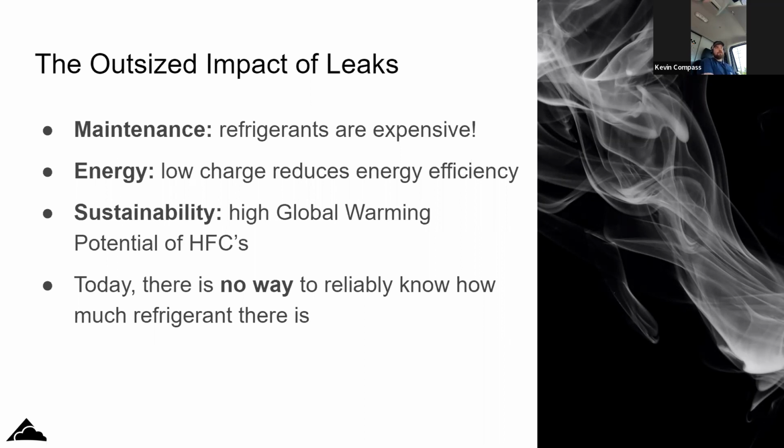So I generally tell guys, don't stop leak checking until you've covered every inch of that store that you can get to. And like Brian said, sometimes you may not find the leak the first time, that first go at it. You may have to come back with a scissor lift and dig into it. But if you're adding refrigerant to the system, it went somewhere. So you need to find out where it went.